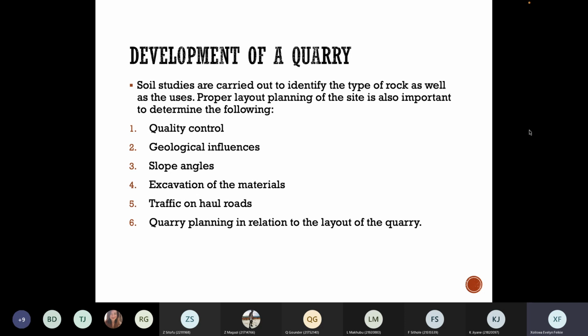So sometimes they will collect the material for either the layers of the road, the base, sub-base, subgrade, or for the surfacing. They will blast, or use explosives, to fragment the rocks and then use crushers, right? So they will crush it to a 19 millimeter.